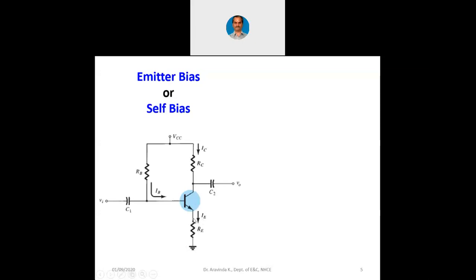This VE is going to reverse bias this PN junction because the cathode is connected to the plus side here. Across the resistance there will be plus here and minus here. Let me annotate. If the voltage is induced across this RE, then we measure this VE across RE with the plus at the top and minus at the bottom. Now this is VE.